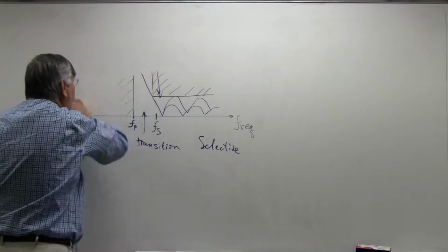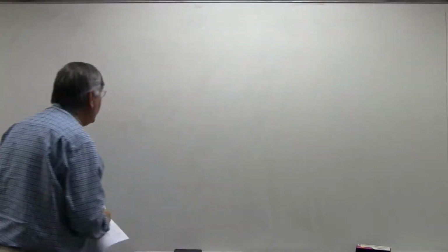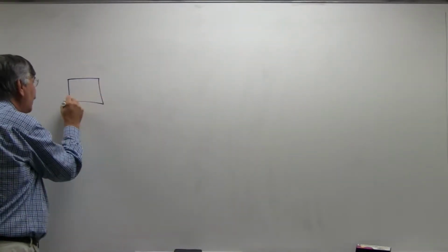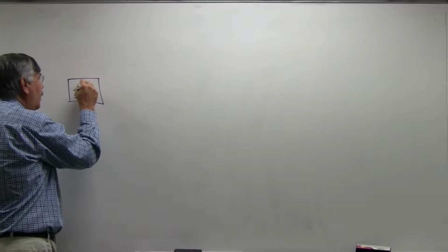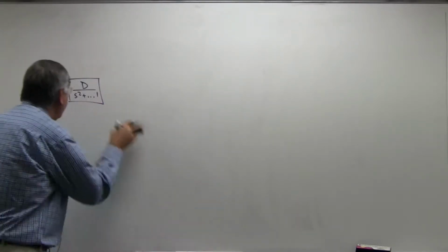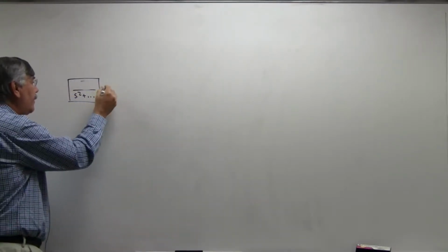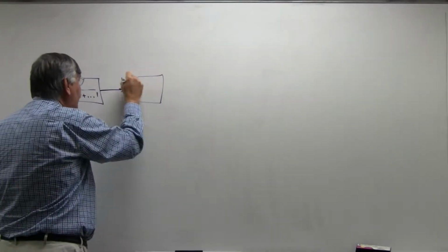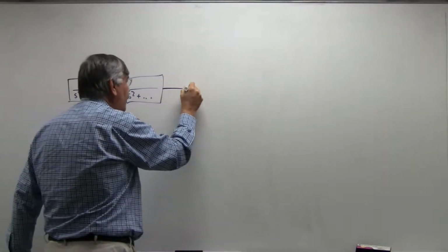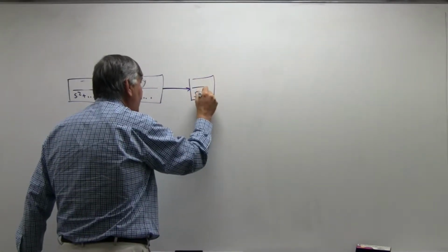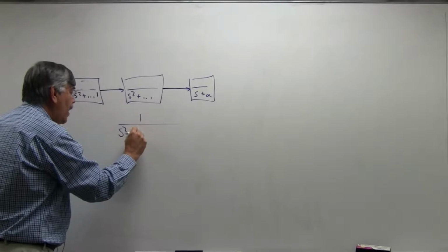We've talked about, again, low-pass filters. The basic unit of the filter, so one way to build a filter is to put a cascade of different things. So we could put one second order filter here with a denominator and a numerator term, and this would be a so-called biquadratic section. It's got two poles. We could maybe have a second pair of complex conjugate poles here with a different set of things. And if it's an odd number of poles for the overall system, then we might have s plus another alpha. So the transfer function in that case would just be the product of all those things.